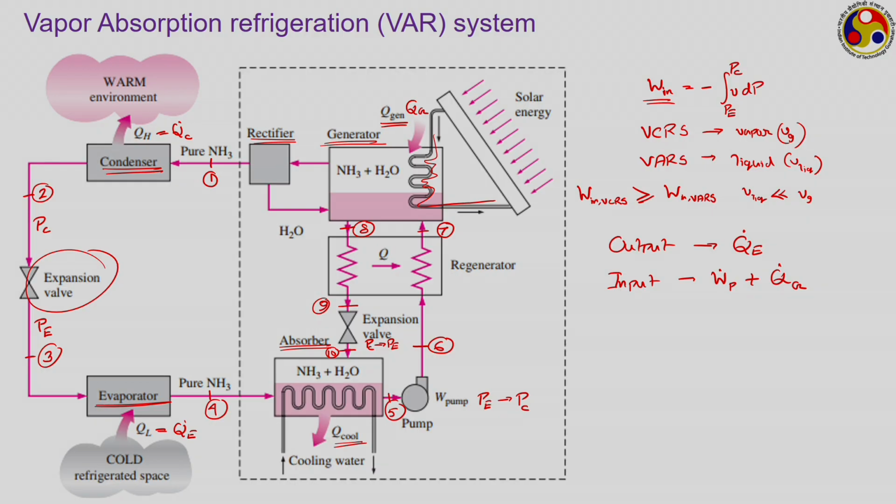So, ammonia water mixture is a very common kind of working fluid combination that we use. Here we are using two fluids. One is the refrigerant, which is ammonia, and the other is the absorber or absorbent, which is water. There can be several such combinations, like a very popular combination where water is used as the refrigerant and we use lithium bromide as the absorbent. That is also a quite common or popular solution, and similarly we can have a few other mixtures as well.